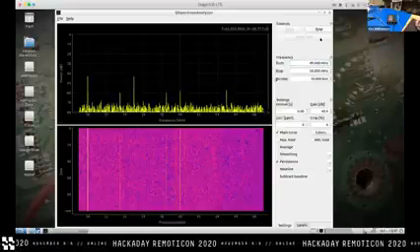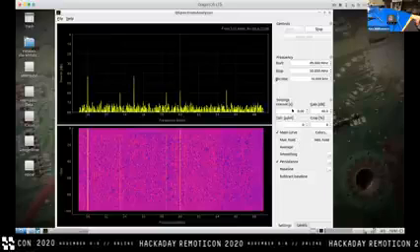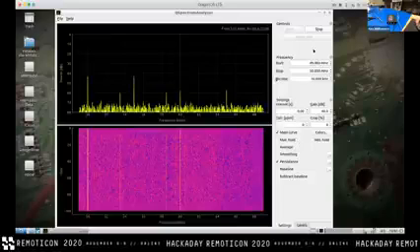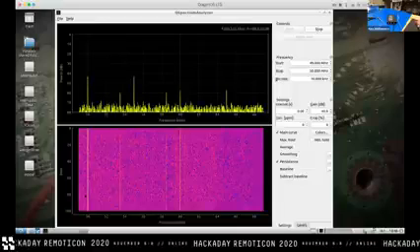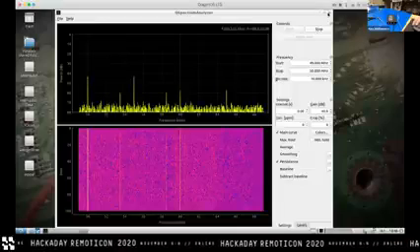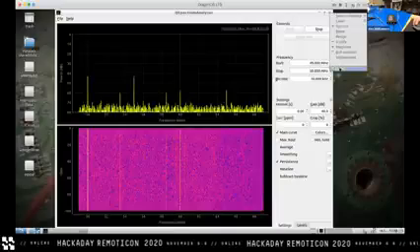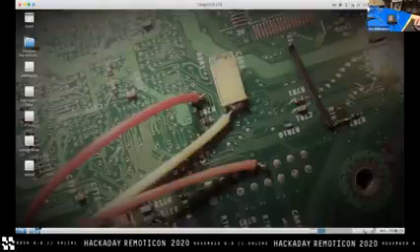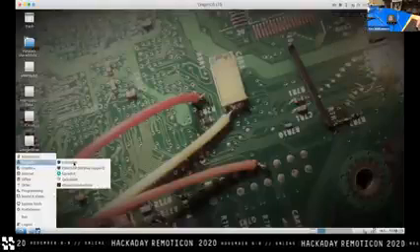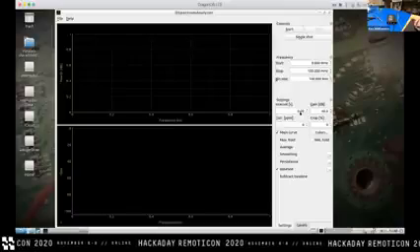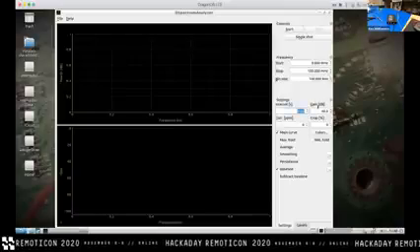Oh my goodness, it's capturing fast enough that I actually think I locked it up. I think I needed to set the interval to 0.01 again. Okay, I'm just going to kill QSpectrum Analyzer and we're going to retry that. As fast as you can might have been overzealous. 0.01.